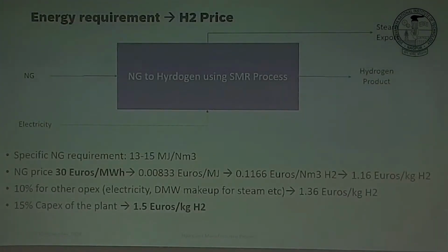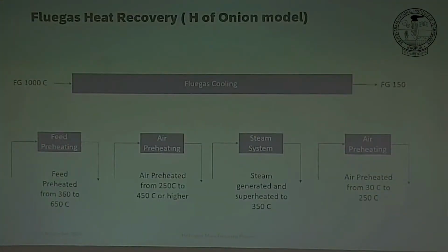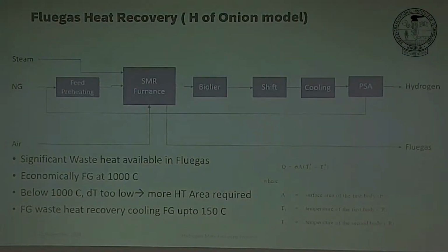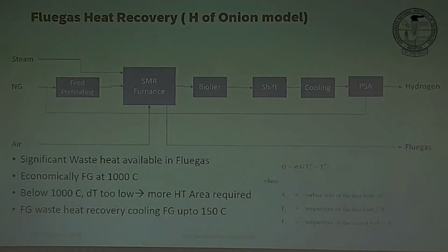Sorry? CO and CO2. So what happened? Yeah, good question. So what happens is you separate your pure hydrogen here, and generally you have 90% recovery of your hydrogen, because we saw during the desorption step, you need pure hydrogen to remove your gases which are adsorbed, right? So you will have somewhere around 89-90% recovery here, and all the CO, CO2, a little bit of water, they all end up here in this tail gas.